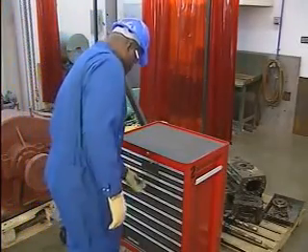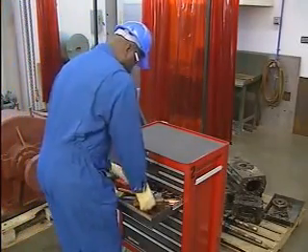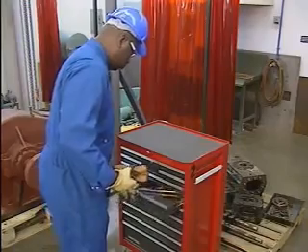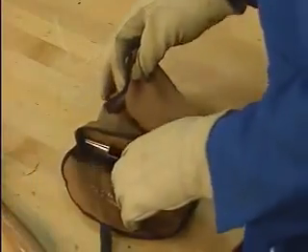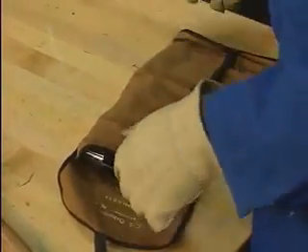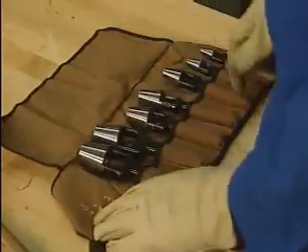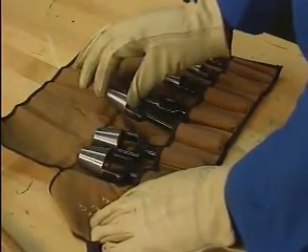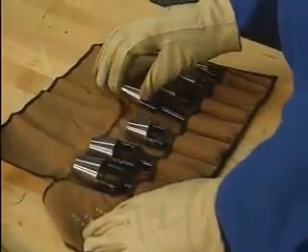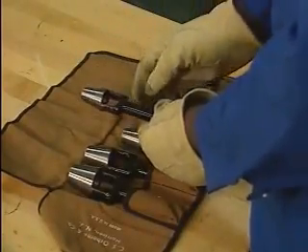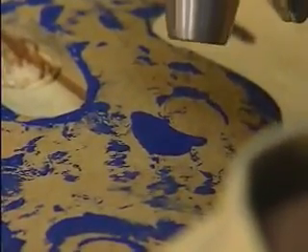When he's finished cutting the gasket to the desired shape, the mechanic uses a hole punch to make bolt holes in the gasket. A hole punch is the best tool for this step because it cuts a clean, precise hole. Well-formed bolt holes are important because they allow connecting bolts to thread easily through the gasket material to avoid tearing or buckling. The mechanic places the gasket on a piece of wood and positions the hole punch over one of